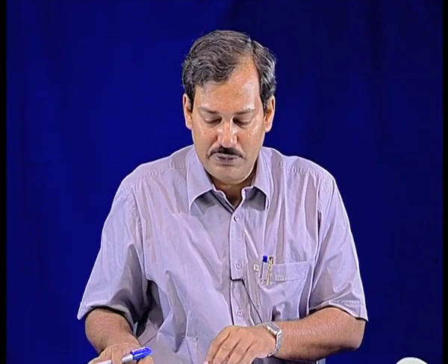If that is the case, there will not be any difference between radiosity and the inherent emissive potential. But that does not mean that it is a black body. It will still not be a black body, but for the special condition that you are attaching to it, it behaves as if J2 and EB2 are the same. That is called a radiating surface.